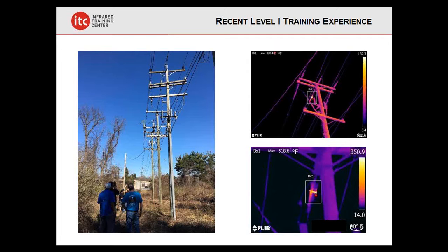That's 260 Celsius. Now, there were some issues going on here in terms of being at a distance, emissivity considerations, and convective cooling. There are a lot of things telling me that this was probably even hotter than what it appears to be right here. But the point is that with the exercise, they found this, discovered it, actually reported it, and the power company came and addressed it.